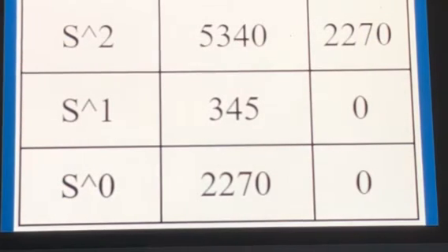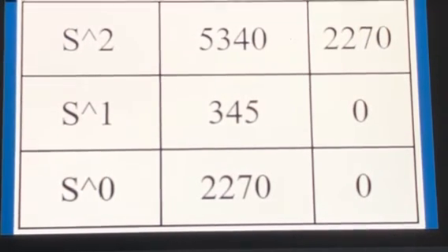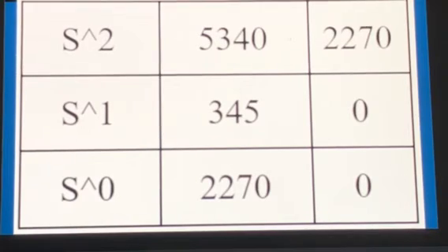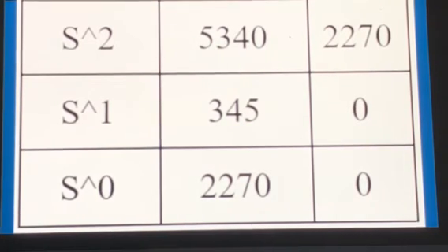In order to further analyze the stability of our transfer function after the Kp, Kd, and Ki values were all added, we used a Routh-Hurwitz table for the closed-loop transfer function. It is clear that the first column of numbers are all positive, indicating that the system is stable.